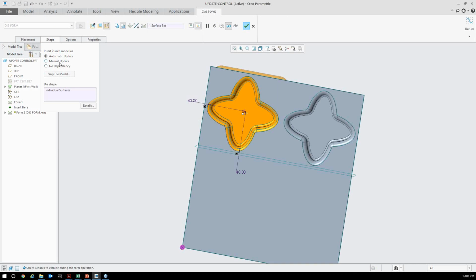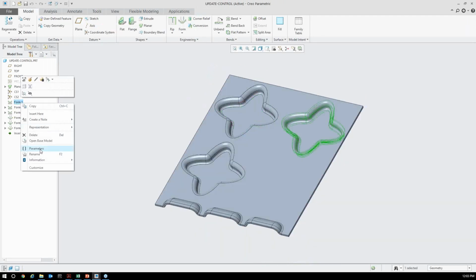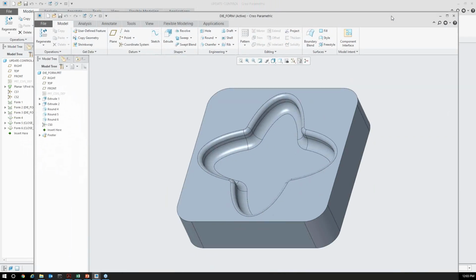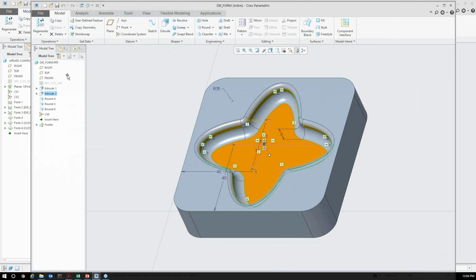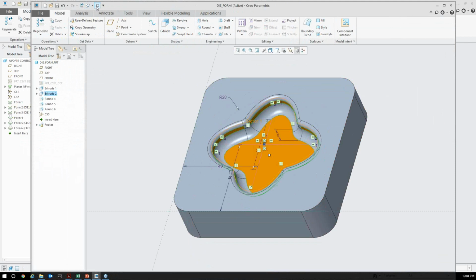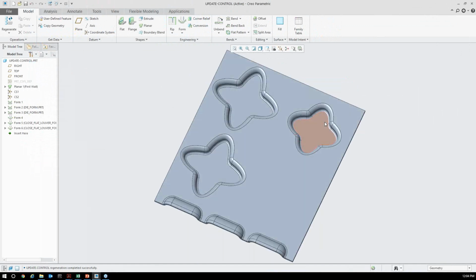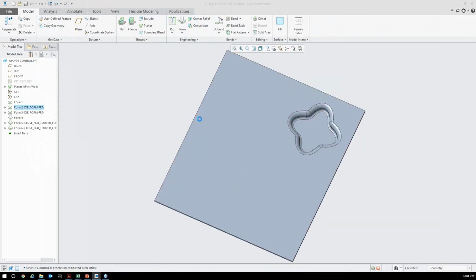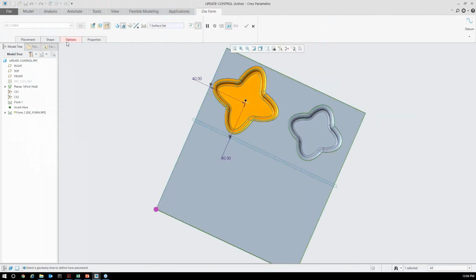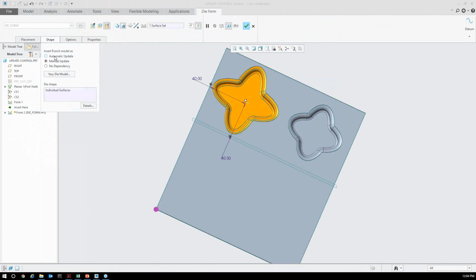Oh, well, we didn't change the actual geometry for our die. Just cancel this. And go back and change that die. I think that was 28 units. It looks like it regenerated, so it should be fine. We'll regenerate this. And this does update. Again, do the same thing over here. Okay, so right now it does not update. If we change it so it does update,